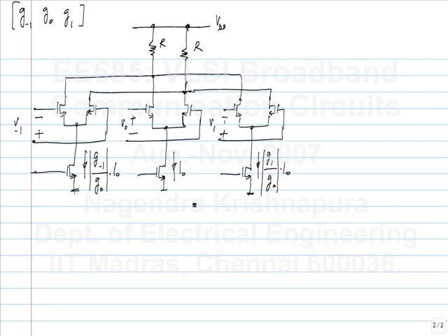Now, first thing is we can use Nmos or Pmos transistors. Which one would we choose? Pmos. Okay, one answer is that you can choose Pmos so that you get voltages with respect to ground. Yeah, now the counter argument can be that it is differential, so its common mode value doesn't matter. But it is still true that Pmos gives you not a common mode voltage of 0, but a common mode voltage that is closer to 0. Okay. So what else? How would you decide between choosing Nmos or Pmos?